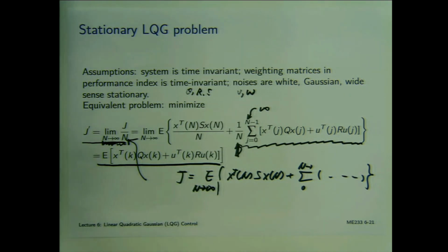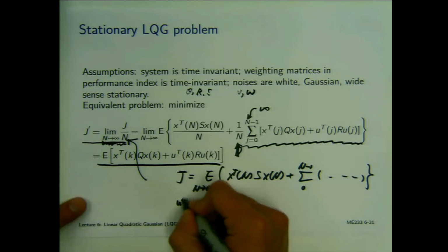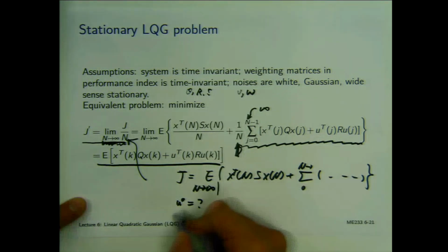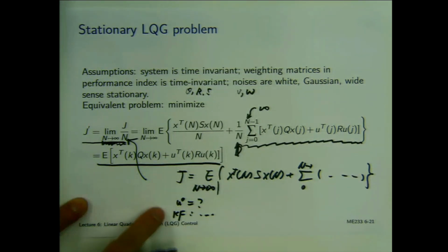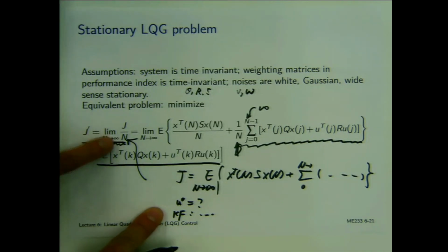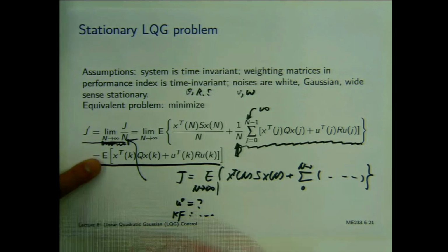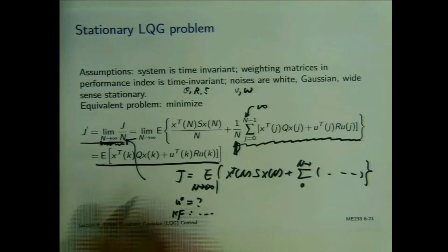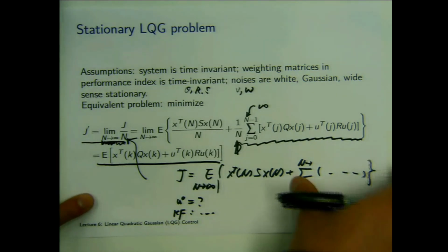That's the intuition behind this. So someone tell me, if I add this n here, will the solutions change? Like my optimal control law, U optimal, and then the Kalman filter equation. Will these solutions change because I have added this n? No, right? Because this is a scalar. So a scalar doesn't change the optimality of the solution. I can use exactly the same control law and the Kalman filter for this case.